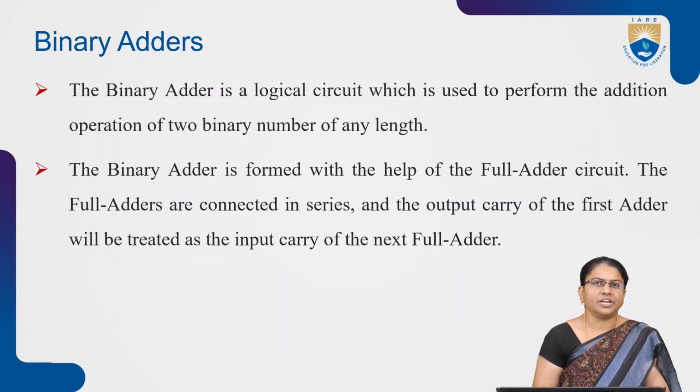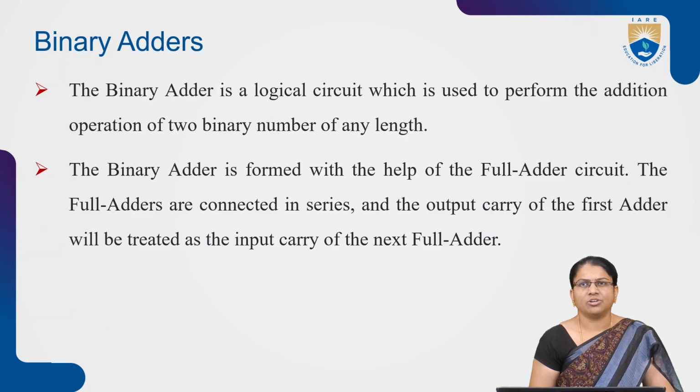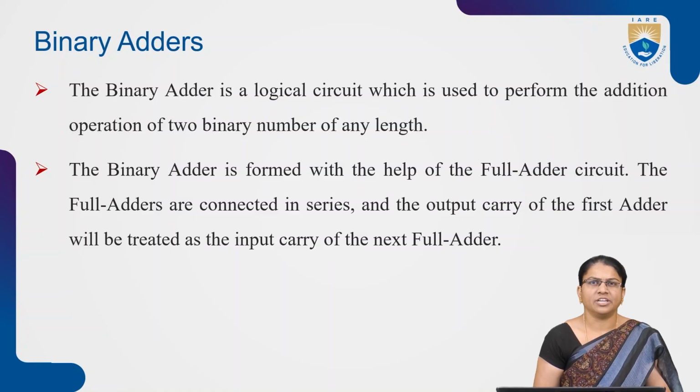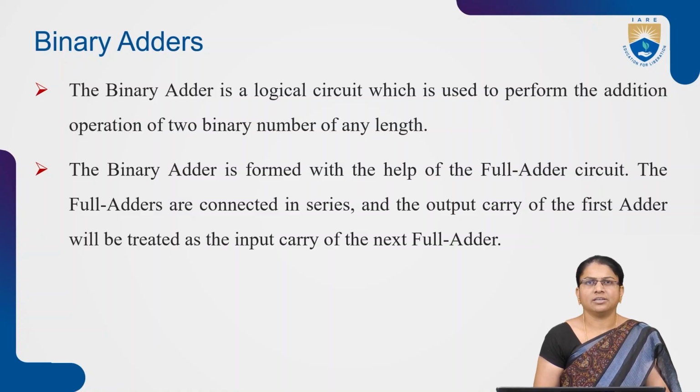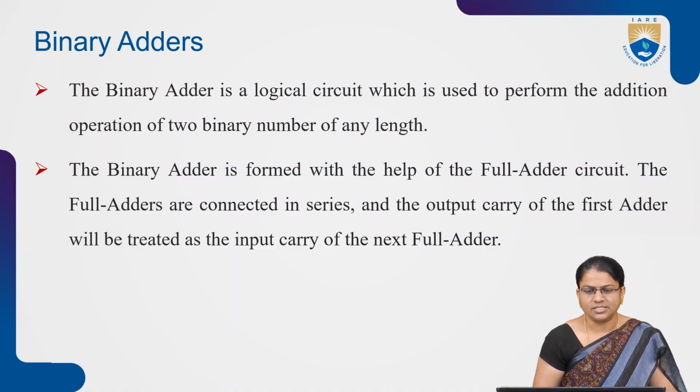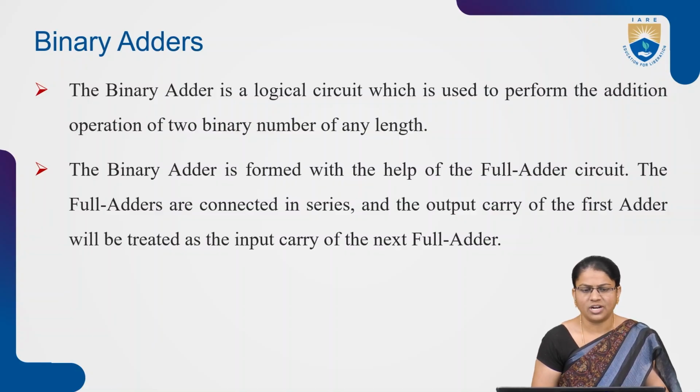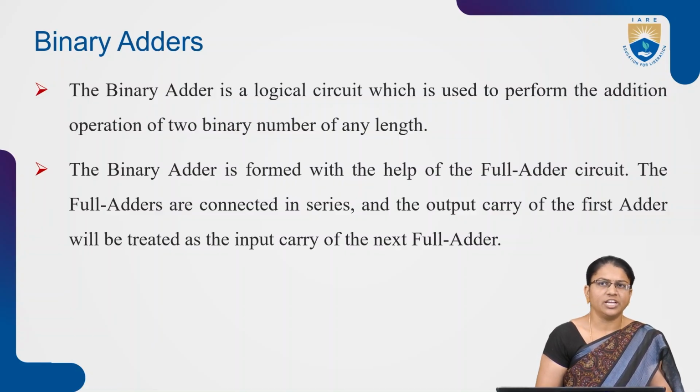What is meant by a binary adder? A binary adder is a combinational logic circuit which is used to perform the addition operation of binary numbers of any length. It may be a 2-bit, 3-bit, or 4-bit length. Depending on the number of bits, by adding the bits, a carry is generated, and you have to add that carry to the remaining bits. The binary adder is formed with the help of full adder circuits. The full adders are connected in series, and the output carry of the first full adder is treated as the input carry of the next full adder.